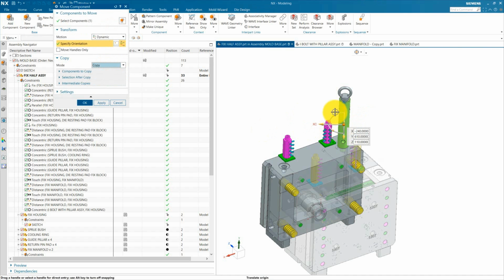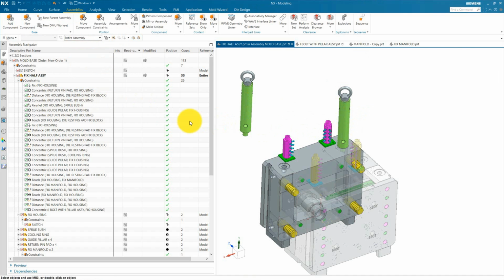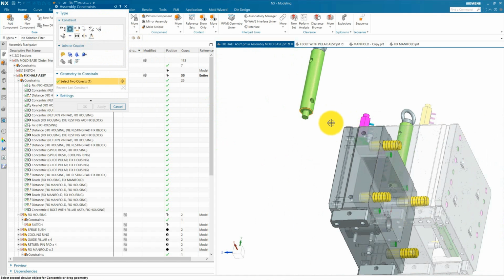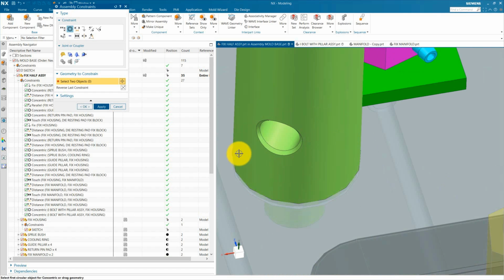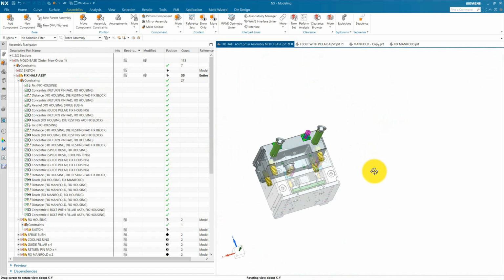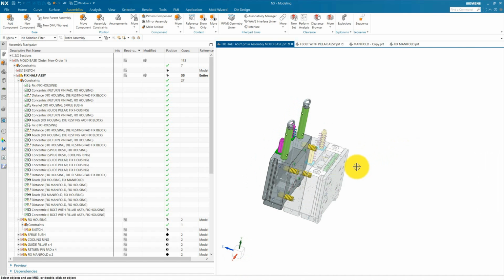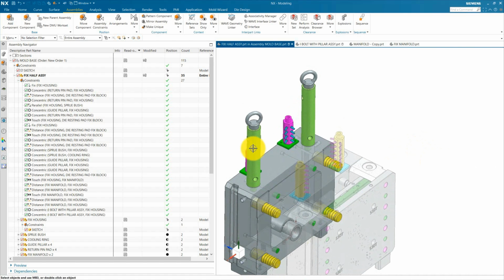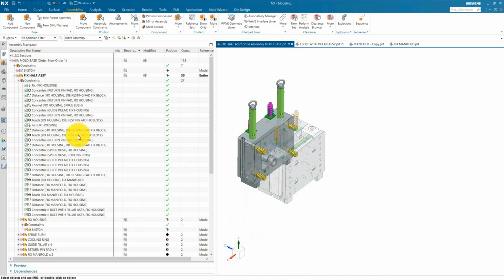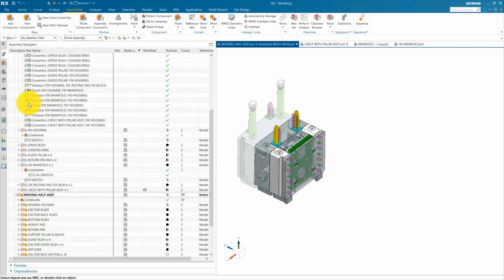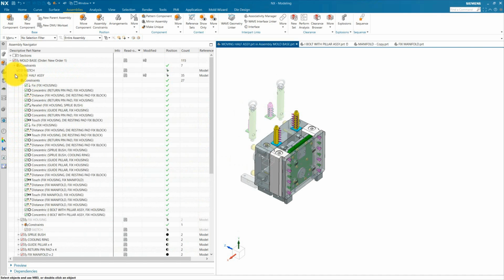Okay, the same, we copy it. For example here, copy and one more copy, and we use assembly constraint, select this bottom chamfer and this bottom face and apply this. Okay, you can see the eye bolt and pillar is assembled. Same we are going to do with our moving hub assembly. So activate our moving hub assembly, hide this fixed hub assembly.